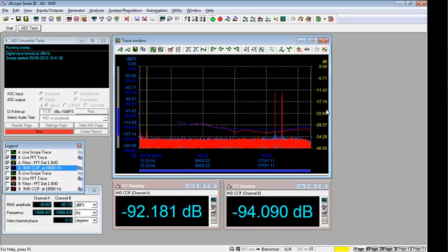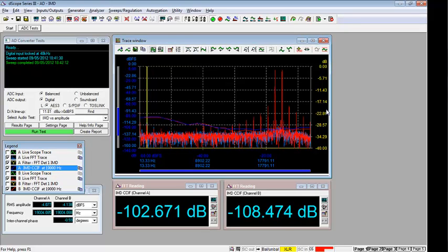Again, this test is using our clever adaptive FFT script, which is deliberately choosing larger FFT sizes when the distortion results reduce in amplitude to a point where they would be potentially getting close to the noise floor, and we then need to use a larger FFT size to allow us to clearly see that distortion product above the local noise floor.